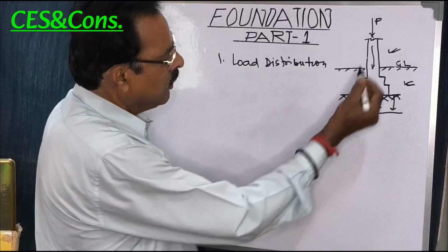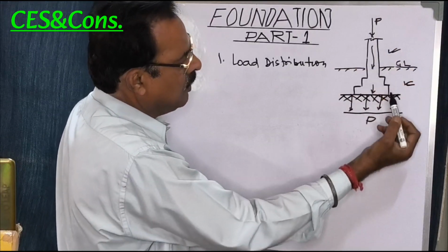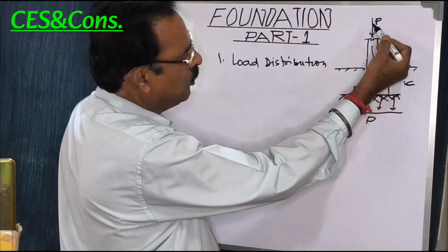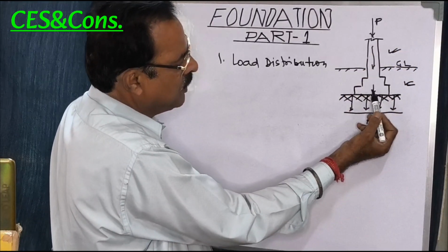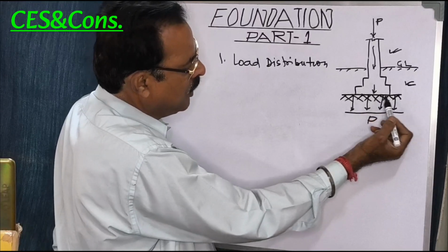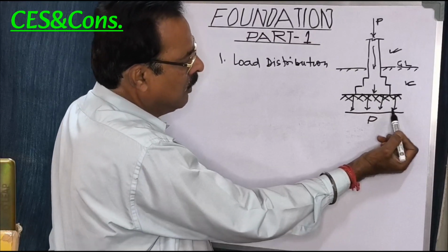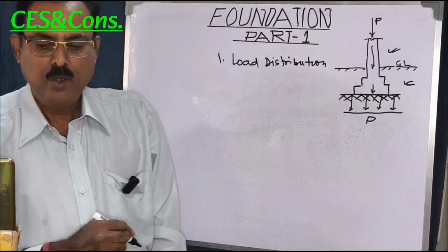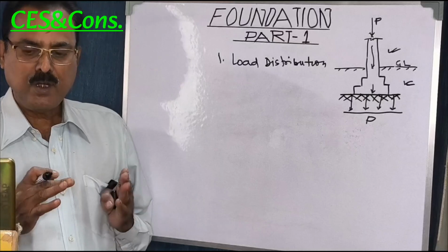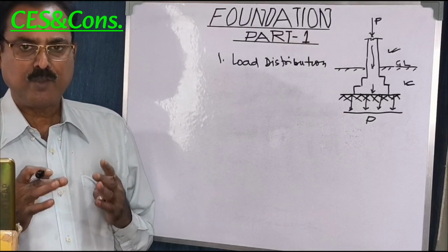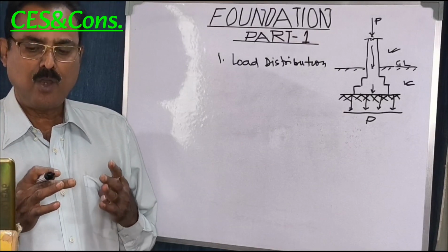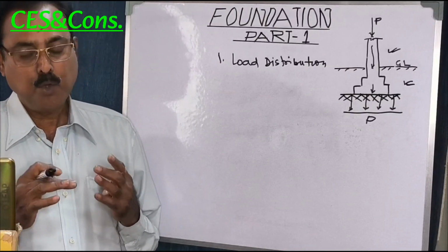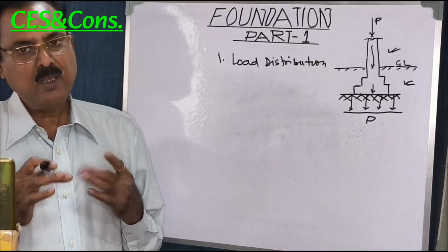The load through the superstructure comes to the foundation and is distributed to the underlying soil evenly and over a wider area. The foundation evenly distributes the weight of the structure over the soil or rock beneath it. This prevents excessive stresses and potential settling or sinking of the building.